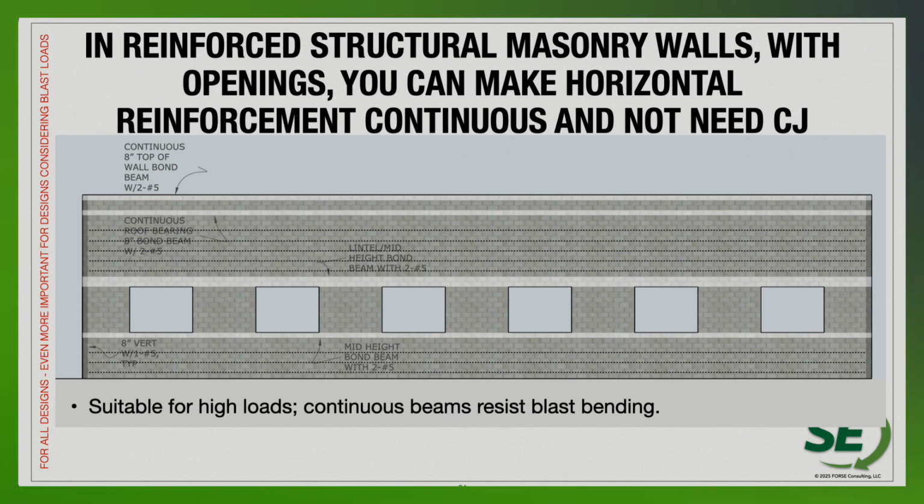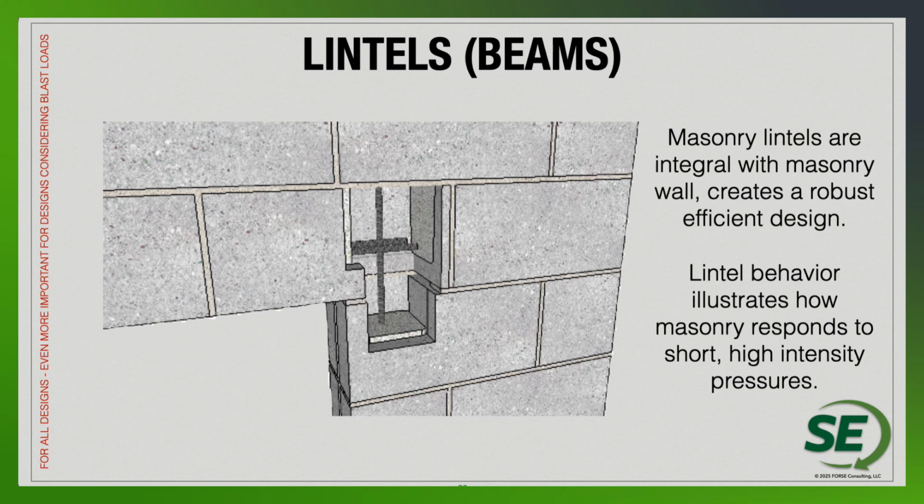So it's going to be very suitable for high wind load, tornado or storm shelter type situations, but it's also going to be very good for blast loading and that high impact loading that you'd have in that design. So just a little bit of a highlight about the lintels. The lintels in these elements are going to be very, very critical, making sure that we have masonry lintels where we have that horizontal reinforcement that crosses with the vertical reinforcement. That two-way distribution of force is going to be really important and very critical to taking those loads.